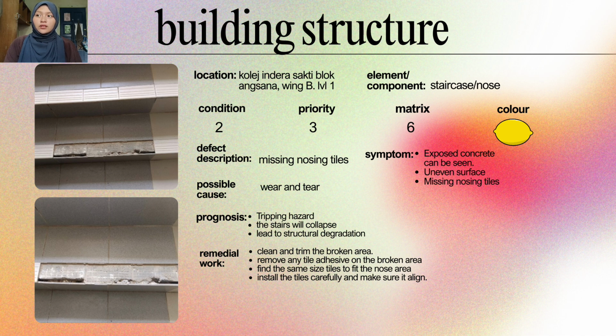Next is remedial work. First, clean and trim the broken area, and then remove any tile adhesive on the broken area. Find the same size tile to fit the nose area. And lastly, install the tile carefully and make sure it aligns with the other nose.